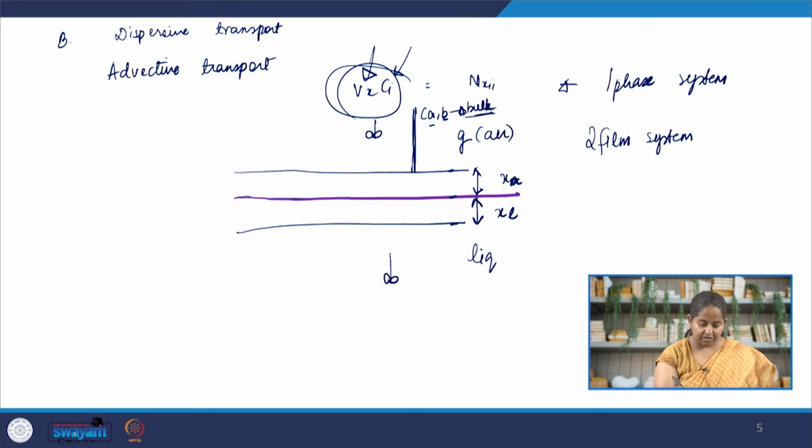This straight line represents constant concentration, assuming that the x-axis is the concentration. So the concentration with height is constant, it's well mixed in the bulk gas. And then we have a thin film here, and here the concentration falls. This is where a small film is formed, and by the time we reach the interface, the concentration in the air becomes I. This is not bulk concentration, because you see within the film the concentration is slowly tapering away, and then the contaminant is transported. Remember, the contaminant is being transported towards the liquid phase.